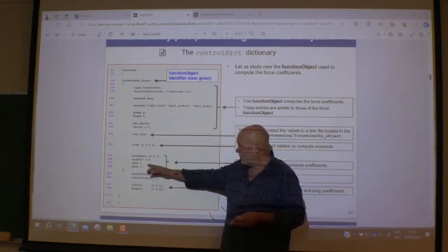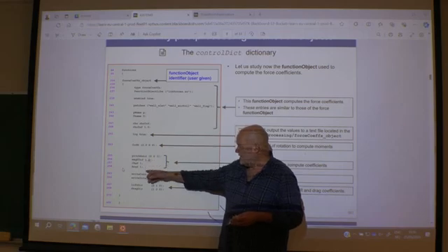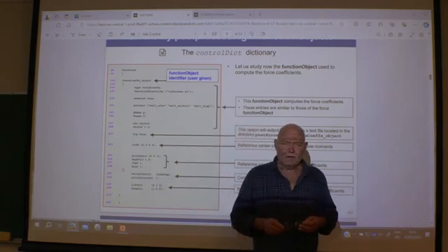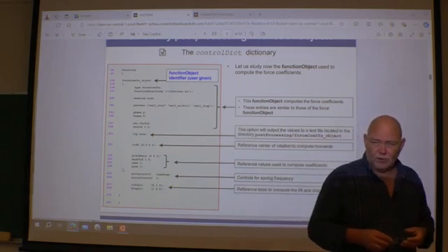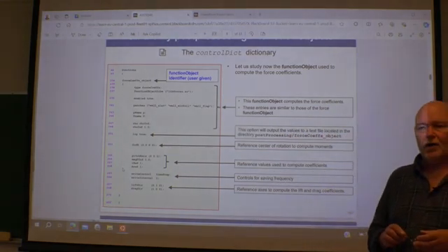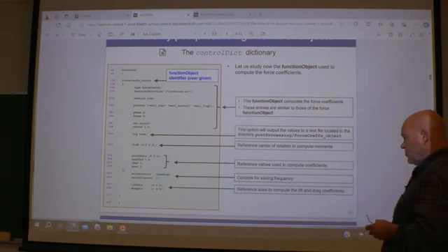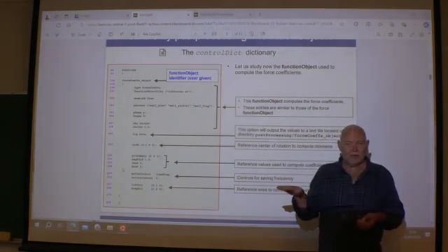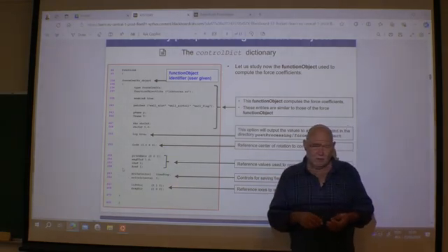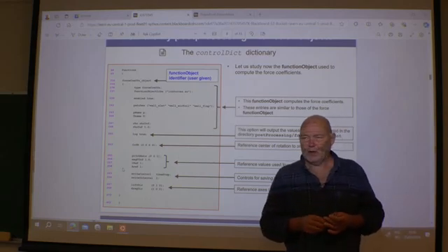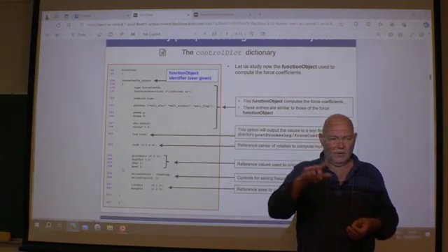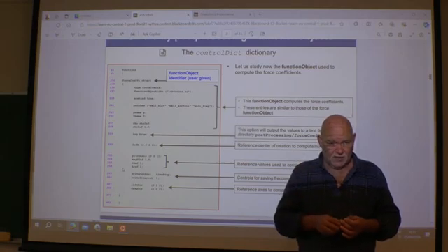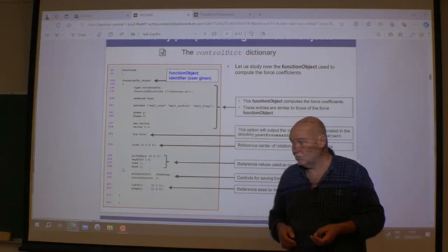And also here, important, you need some reference parameters when you do the calculation for a drag coefficient or a lift coefficient. You take the force in Newton and then you scale by what? You use the dynamic pressure, 1/2 rho u squared, and then times an area.